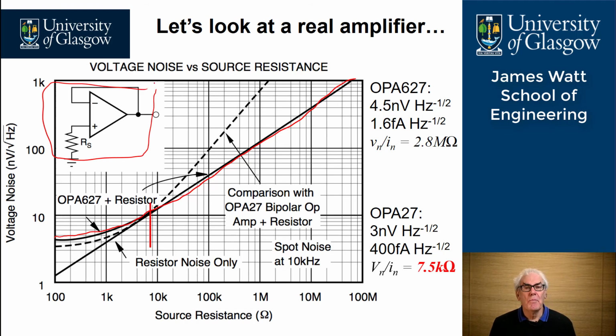Our optimum point is at this point here, when we calculate that the noise resistance is equal to the noise voltage divided by the noise current.